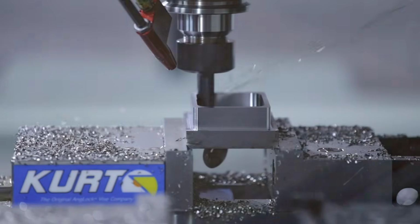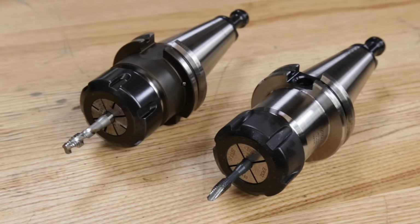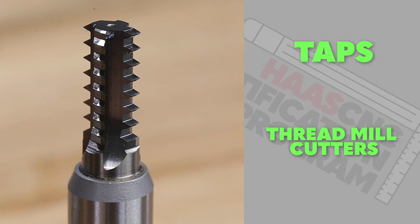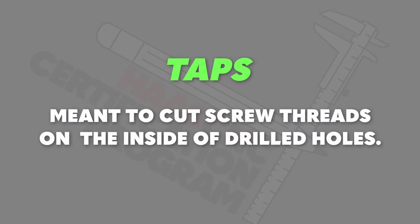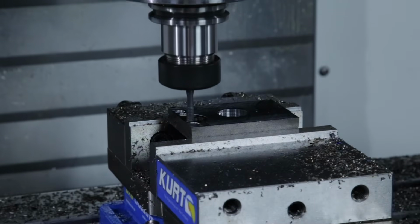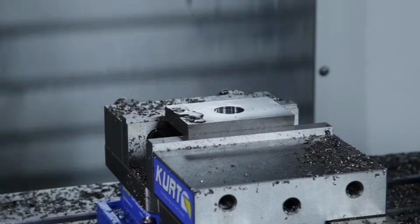The last in our group of common mill cutters are ones designed for cutting screw threads. There are two basic types, taps and thread mill cutters. Taps are relatively simple. They're meant to cut screw threads on the inside of drilled holes. Each different size tap has a specific hole diameter that needs to be drilled before the tap cuts threads on the inside of the hole.